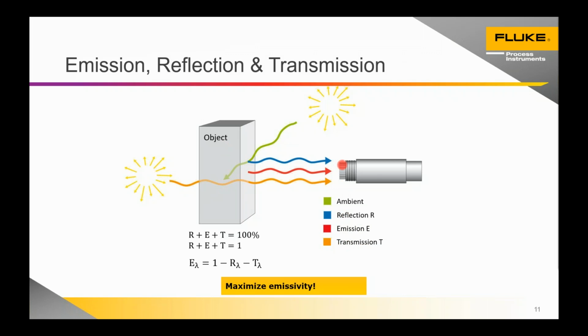Transmission for us applies to our optical system, but also if you have a secondary optic or window in terms of a protection window or looking into an oven, sometimes we can use it to apply gain in a kind of field calibration sense. If you have to work with dirty or scratched windows in between repairs, the sensor can take into account all of these in how it calculates its temperature. The biggest challenge is to know what they all are and have the means to get that information into the sensor.